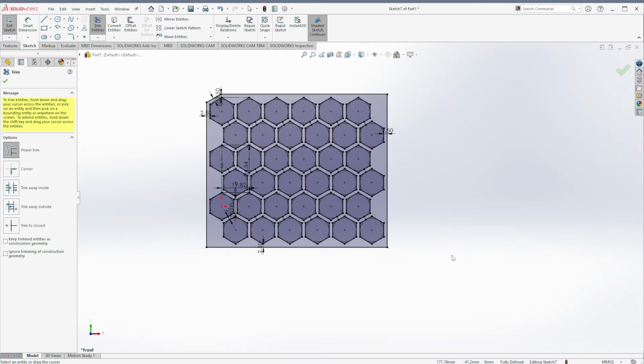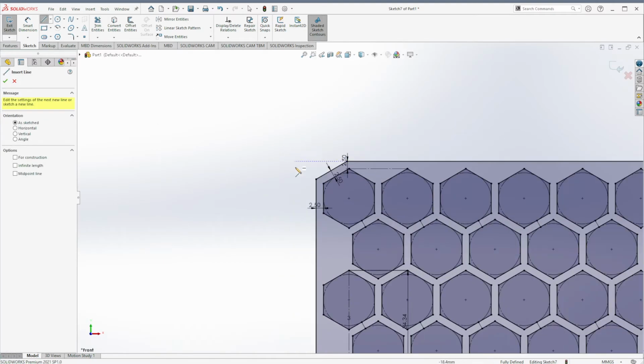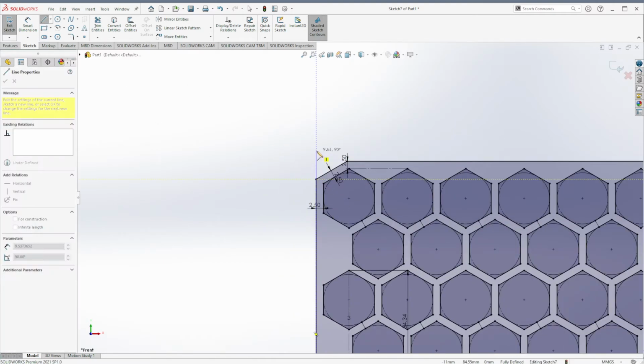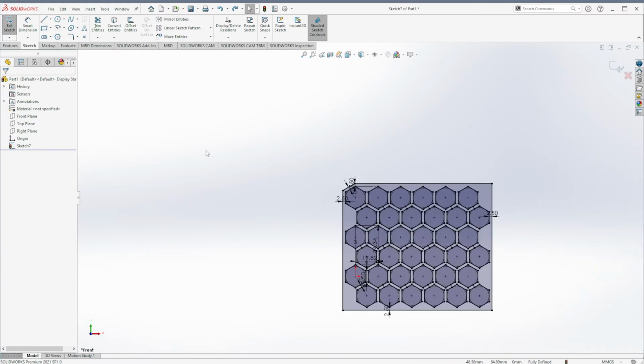Basically what you're looking for is to keep the area that you want material to be light gray, and SolidWorks will figure it out. If you have incomplete edges, like for example, if we had not fully finished that trim and there was a piece just lying there, SolidWorks will get upset. Also avoid blue. Everything should be fully dimensioned.